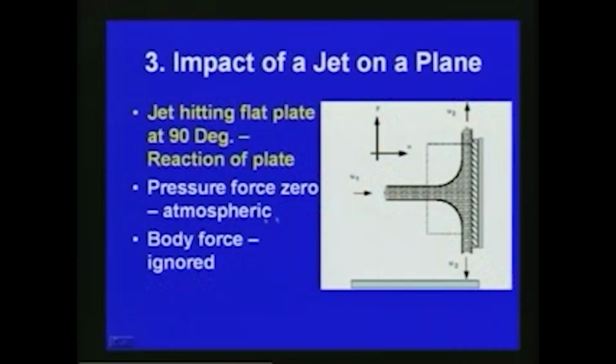Now, all the pressure force here is 0 or atmospheric, and this is the control volume which we consider. The control volume is with respect to this plate, where the jet is impinging on the plate. The body force in this particular case is ignored.